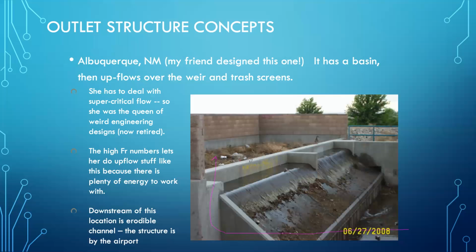This wall right here that the bird is sitting on, the flow goes down there, up and out here as you see it, over these screens, and then the water goes that way and returns to the stream. So this is strictly, apparently strictly, a water quality feature. And the goal is to get the solids out of the water.